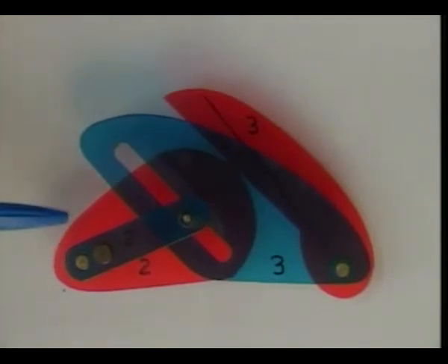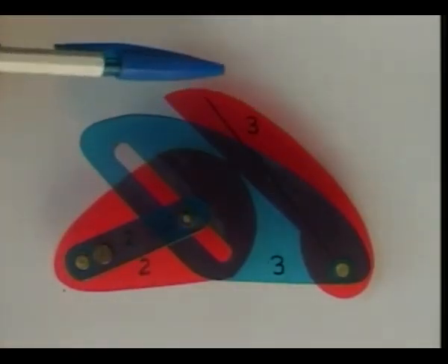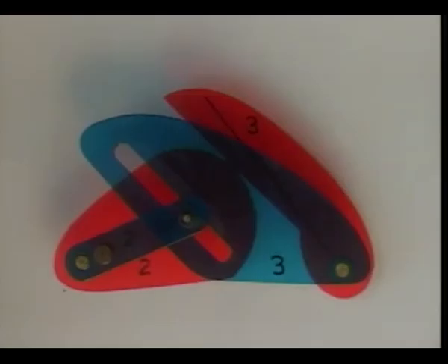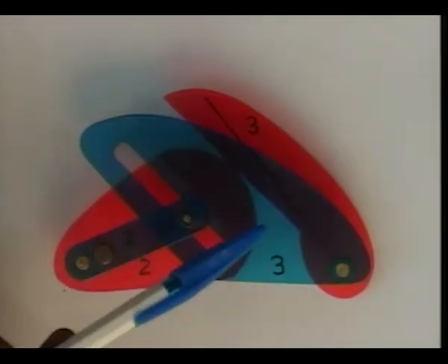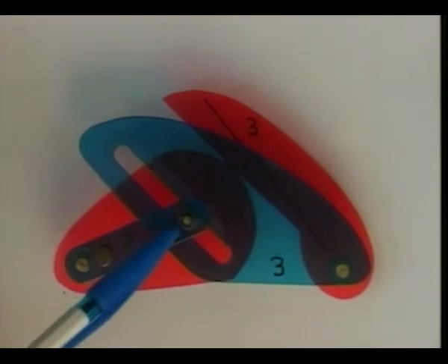Here is a higher pair mechanism between link numbers 1, 2 and 3, and the center of curvature of body 2 at the contact point is here, whereas body 3 has a flat or straight contacting surface. Consequently, the extra link gets a prismatic pair between body 3 and that extra link, and a revolute pair between body 2 and that extra link.